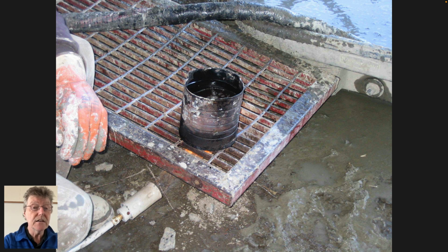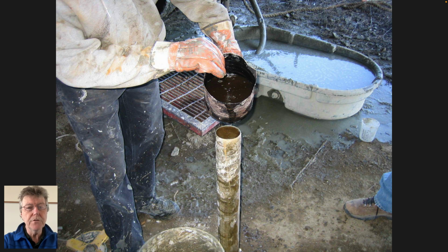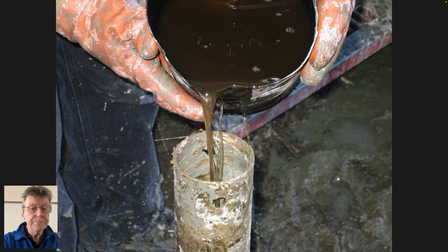And to seal it, you seal it with paraffin wax. So this is just a can. This is a tiger torch. This is actually from the clothes people are wearing. It's December in Boston, cold actually. And so you melt the paraffin wax, and then you seal the top of the sample and the bottom of the sample so that you seal in the moisture content and send it off to the lab.